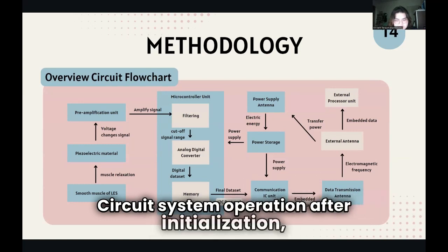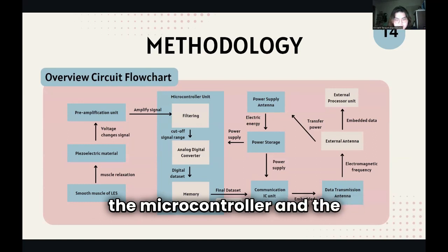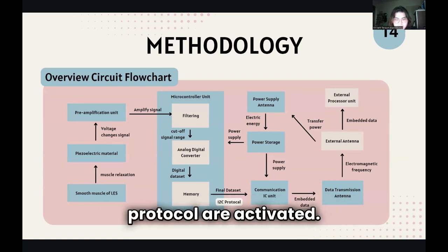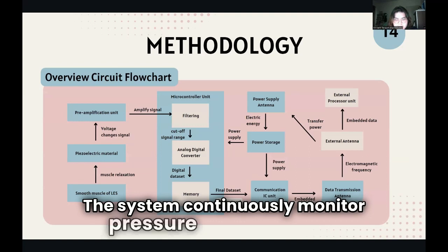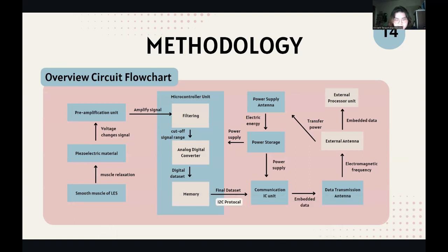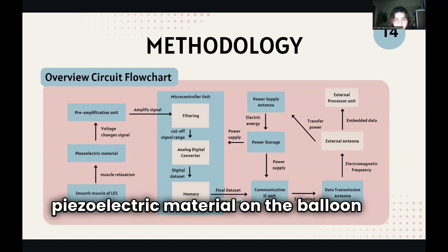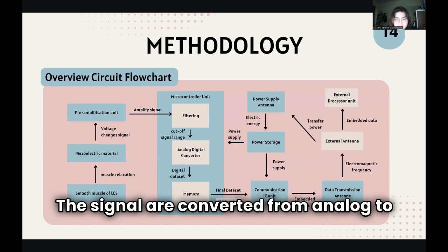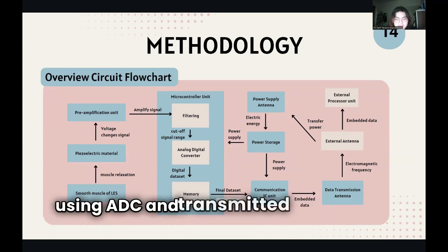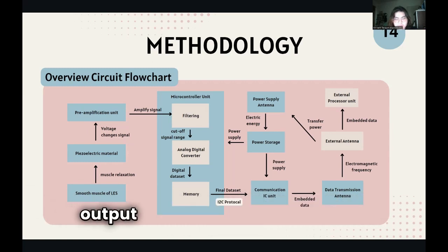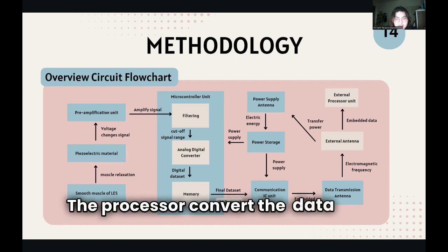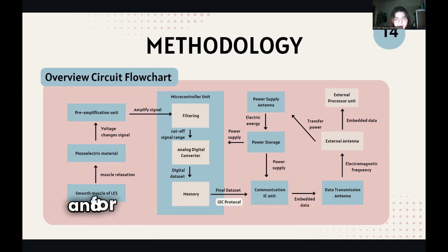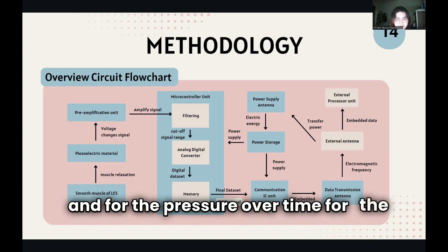After initialization, the microcontroller and the communication protocol are activated. The system continually monitors pressure data from the piezoelectric material on the balloon and amplifies the signal using the analog front-end unit. The signal is converted from analog to digital using the ADC and transmitted wirelessly to the external processor via I2C protocol. The processor converts the data to pressure units and plots the pressure over time for analysis.